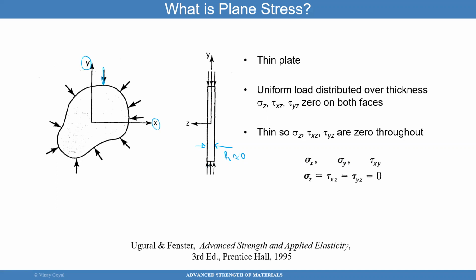Okay, so it turns out that in this assumption, what we're saying is that through the thickness stresses are 0. So any stress corresponding to sigma ZZ is 0, and I'll explain why that is the case. In plane stress, if the body is fairly thin, I can make this assumption. Why is that?